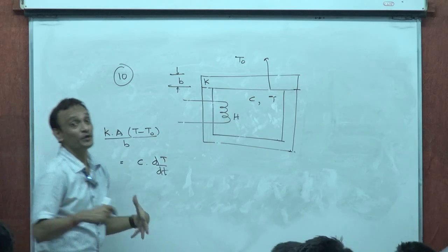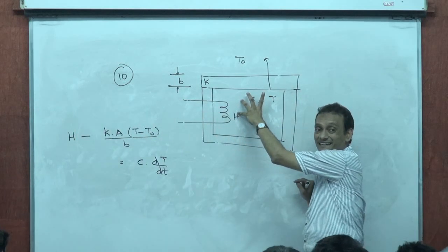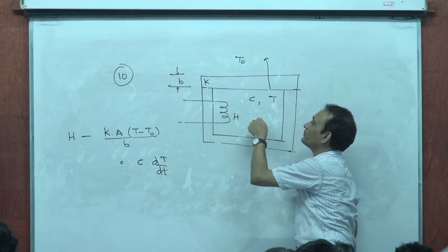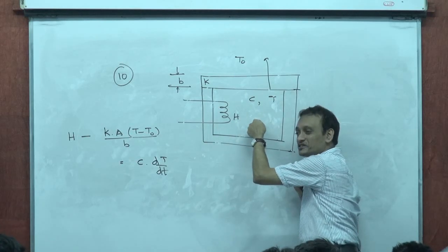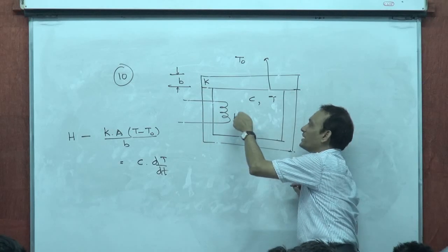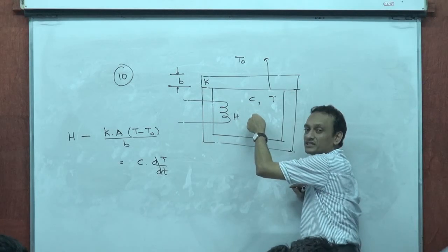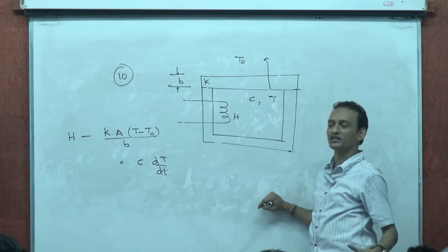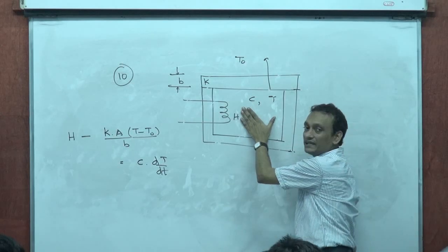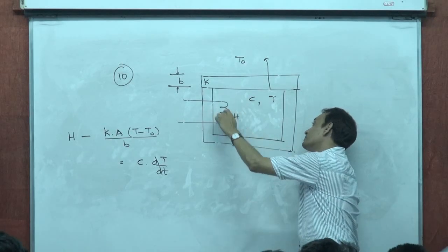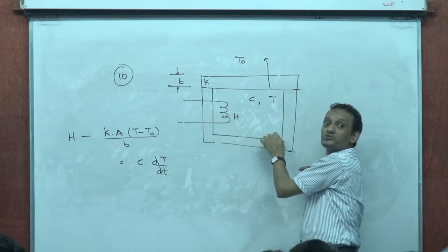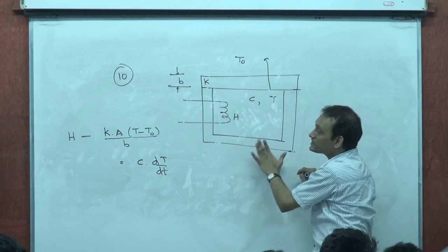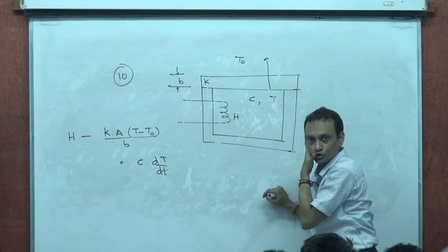Again, the assumption here, we are assuming that this is highly conducting. And of course, it's a fluid, there would be convection currents here, which would bring about thermal equilibrium from instant to instant, but not good enough. We are assuming that there is a very high rate of convection, conduction, everything going on here, and it's maintaining the temperature of this at T. Realistically, there would be a temperature profile inside this also. That's a real life problem, right? So that's how you do this. Clear? Not a problem?